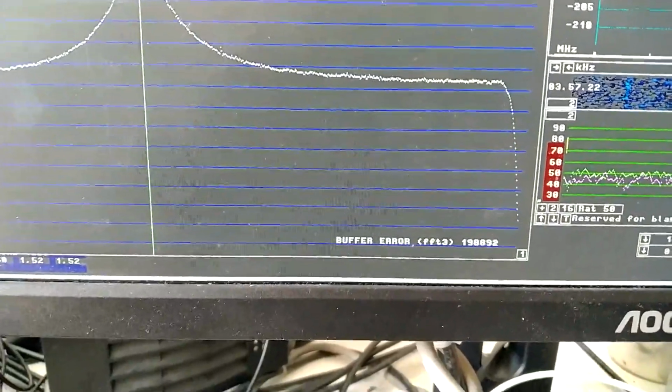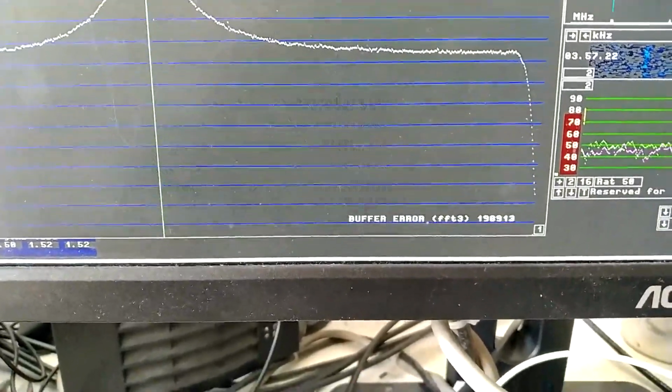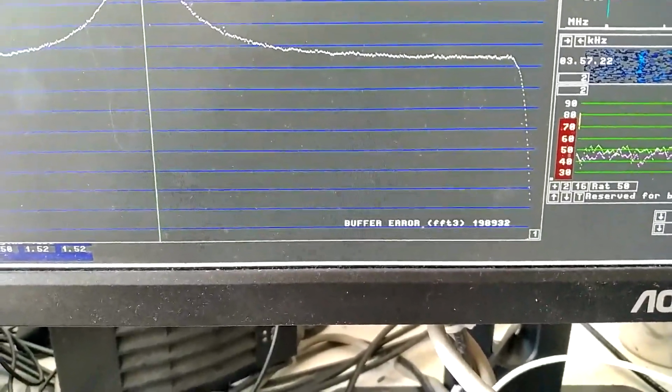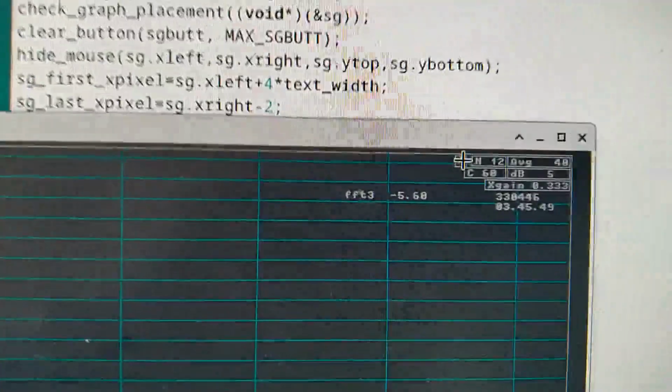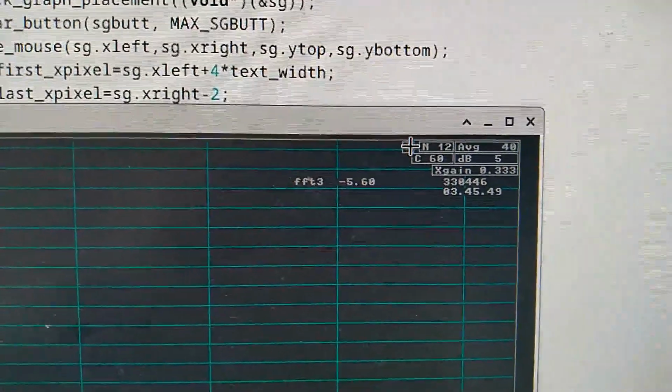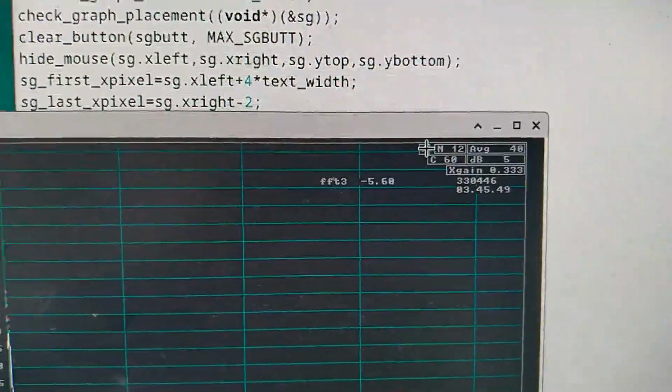This was a too difficult task for Linrad in the current setup. After 3 hours and 45 minutes, it has stopped working because the third FFT buffer is full.